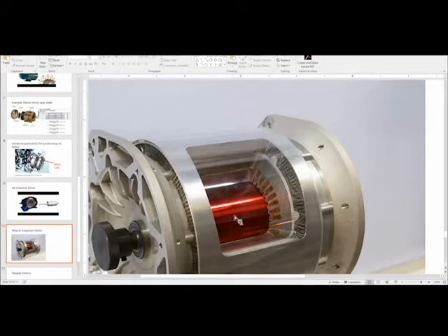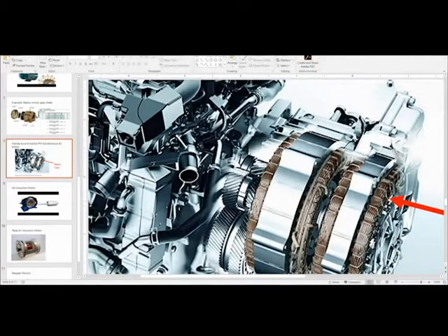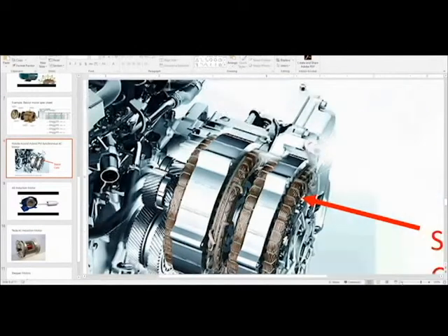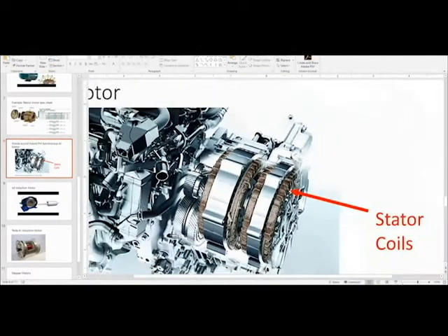So the argument I've heard for why Tesla uses AC induction motors is because they were worried about sourcing permanent magnets for their motors. If you look at the case with this Honda Accord, and what's also used in the Prius, this uses permanent magnets. I mentioned briefly before that permanent magnets are fairly expensive. They're very, very efficient, but you have issues with the location from which you get the permanent magnets. There's not really a good domestic source, and so there's worries about our primary source being a country that we're not always friendly with, I guess.